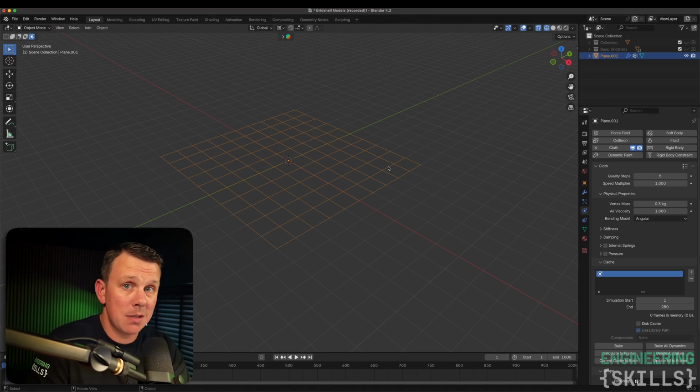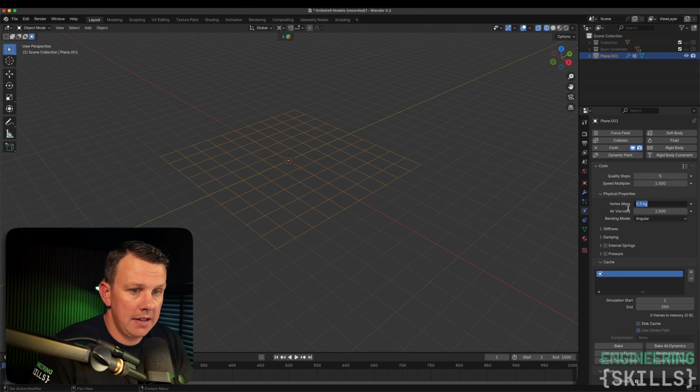So obviously the more mass we have, the more this thing is going to hang down, and you'll see that now when we run some simulations. So we could leave that as 0.3. I'll leave it as 0.3 and you can see what it does. I'm going to ignore all of these different settings because really we're not that interested in the details of these settings with the exception of vertex mass, because all this is being used as is a means of generating our hanging chain geometry. The actual structural analysis of that geometry will happen over in our notebook with OpenSees. So to get this thing running, I need to specify my supports, right?